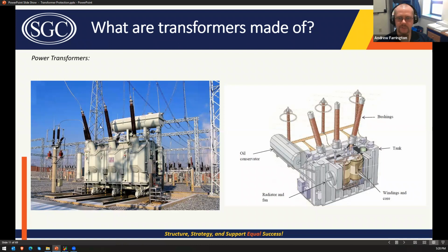Sometimes, if this is the high voltage side, they'll put a lightning arrestor on the neutral if they're not going to ground it directly. So it could be a lightning arrestor. Or, yeah, I don't know. Maybe one's the neutral CT and the other one's a neutral surge arrestor. I'm not sure.